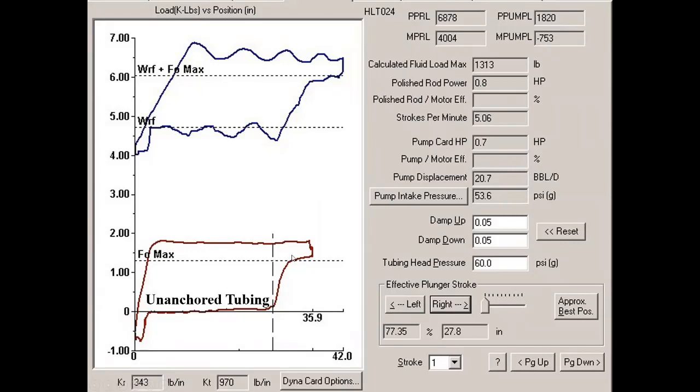In this well here, yes, we have multiple things. We have a thick nose, usually an indication of some friction in the system. We have incomplete pump fillage and maybe a curvature, but I think it's more a fluid pound because I can see the loads are actually above the FO max.